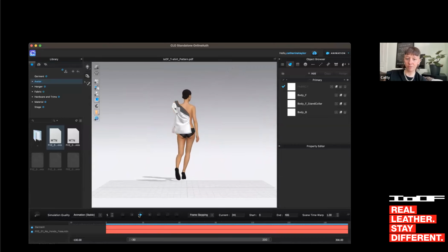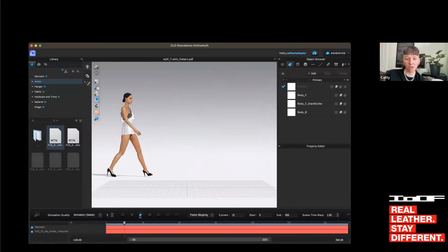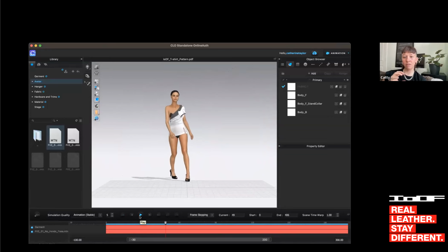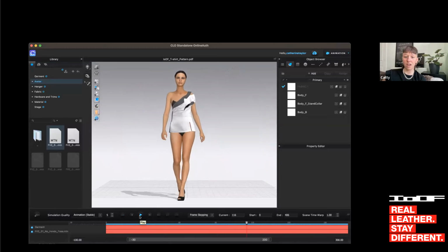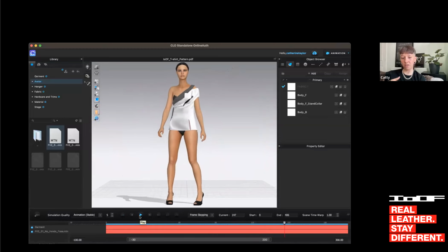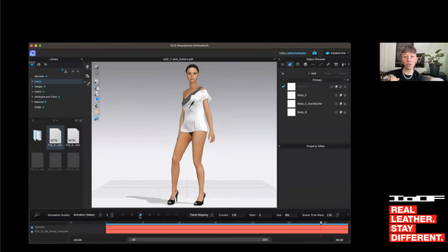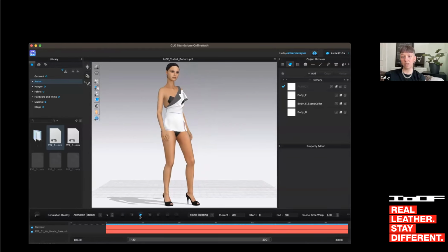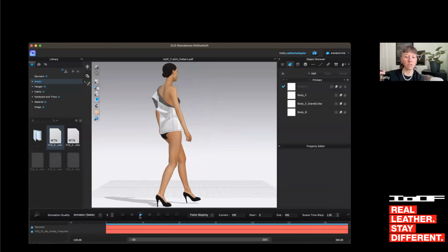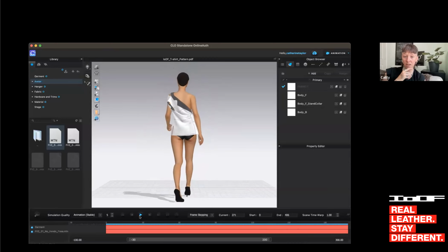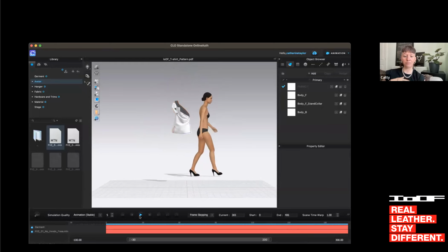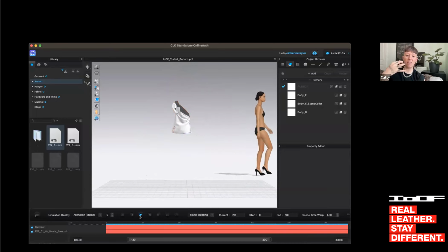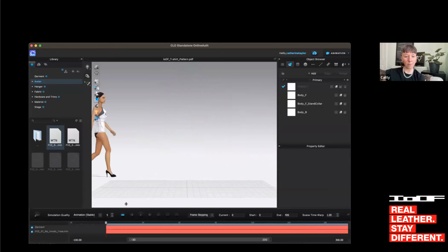And see, that's where I stopped it. You can also change things, like it's quite bouncy. There's a lot of different settings that you can do in the fabric properties. And I'm going to send them a big pack after this of different tactics that you can do. It might be that you really like the floaty-esque quality, or you might want it to be truer to life. This one's quite bouncy, and it's a setting called internal dampening that you can change so that it feels a little bit less like heavy gravity bounce in it, basically.